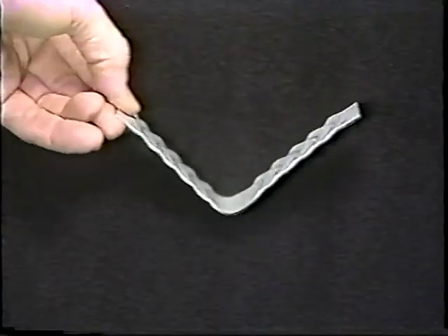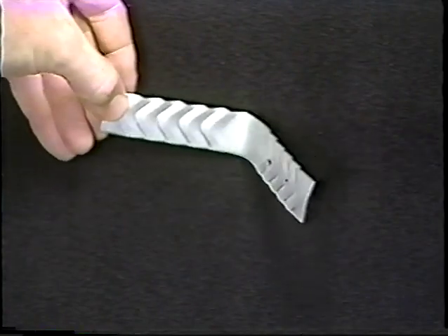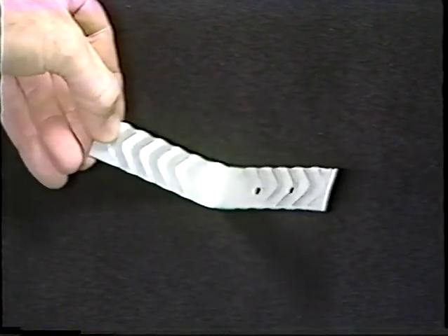Corrugated ties must have a thickness of at least 22 gauge and be at least 7/8 of an inch wide to meet building code requirements. Thicker metal ties are desirable to transfer wind forces better. Thicker corrugated ties are more difficult to bend, so pre-bent ties should be used.